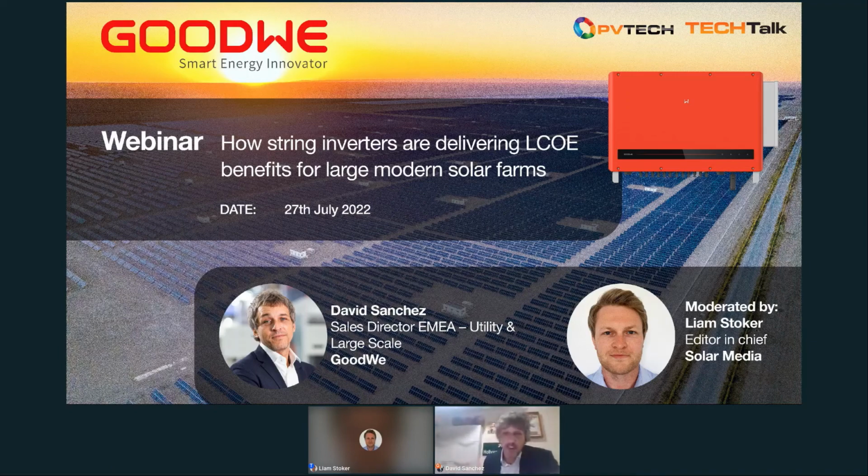On the other side, our GOODWE solution has 2 strings per MPPT in the K version, 3 strings per MPPT in the KM version, right? So the concept behind this is, since bifacial modules are bringing a huge uncertainty, the more MPPTs on site, the way better. So this is where having a solution like ours, 12 MPPT per inverter or 6 MPPT per inverter, you will find yourself with hundreds of MPPTs on site. This is the only way to actually take the most out of bifacial modules.